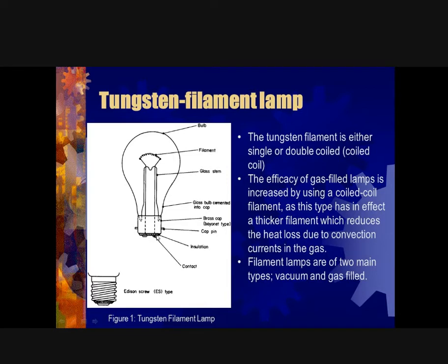For insulation purposes, the two terminals or two contacts are insulated with ceramic type material, again, from touching each other, right? So we don't want any short circuit. Now inside the lamp, there's a filament connection connected straight from the filament to the contacts. One will be connected to the metal cap at the side, and the other will be connected to the center.